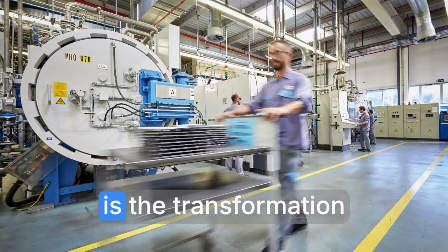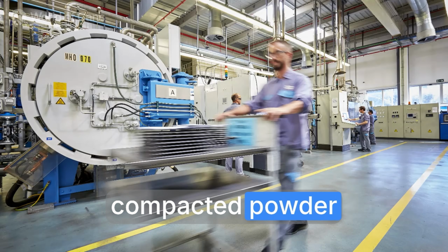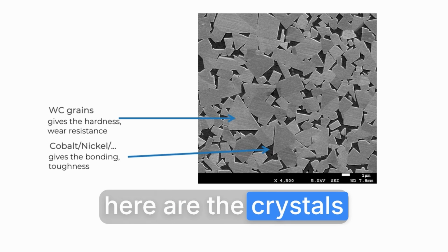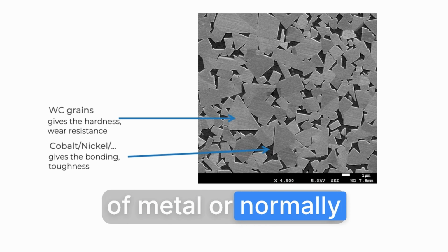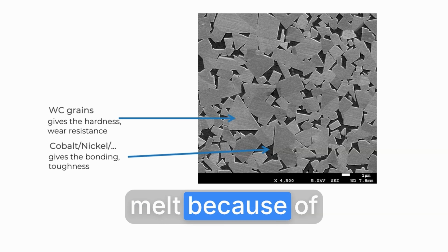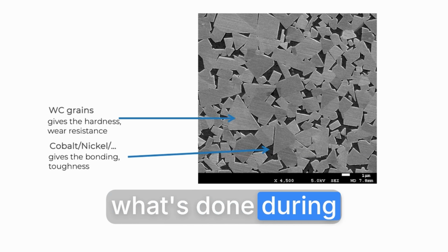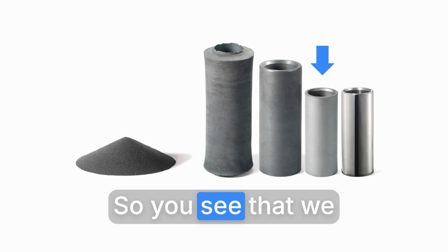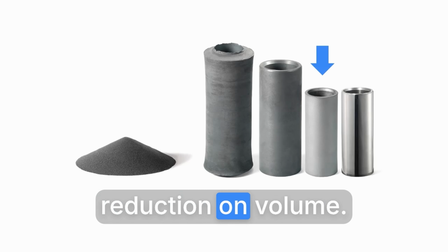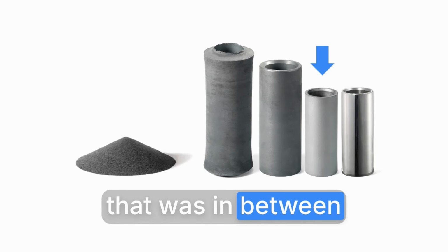The sintering process is the transformation of what was just compacted powder to become a metal. Those black spots here are the crystals of metal, normally cobalt or nickel, and those crystals melt because of the temperature. That process is what is done during sintering. So you see that we have an increase in density with a reduction in volume because we have removed all the air that was in between this green body.